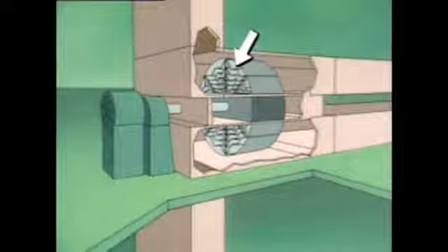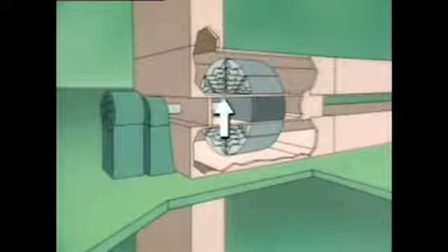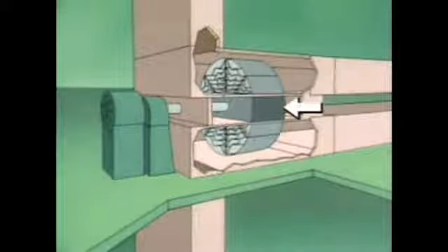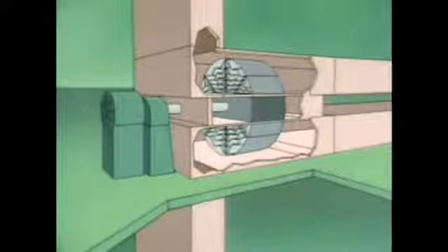This one consists of a series of heating surfaces, or elements, which are connected to a motor-driven shaft. The top half of this heater is in ductwork that routes hot combustion gases from the boiler through the air heater and on to the stack. The bottom half is in ductwork that directs incoming air through the heater and on to the boiler. A seal prevents hot combustion gases from mixing with the air flowing to the boiler.